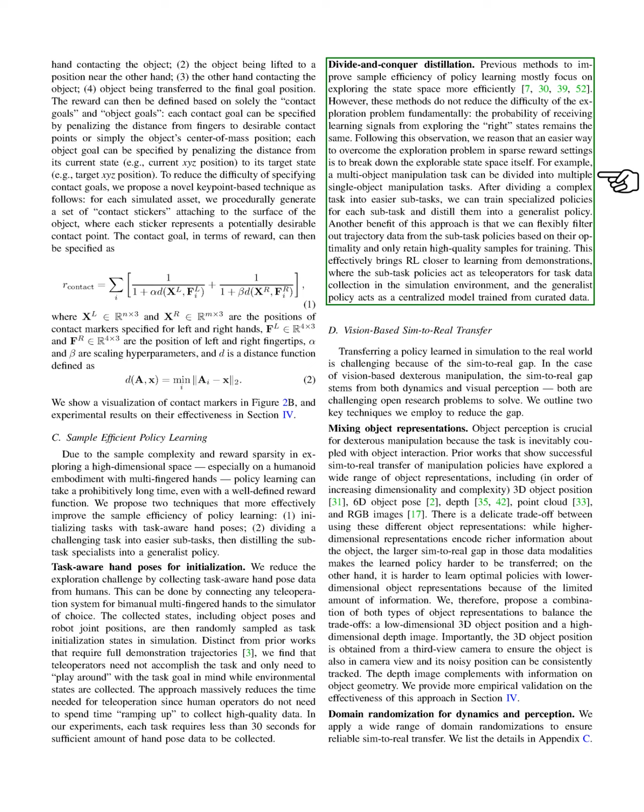In our divide and conquer approach, we suggest breaking down complex tasks into simpler ones, allowing us to train specialized policies for each subtask. We can then distill these into a generalist policy, filtering out only the best trajectory data for training. This method aligns closely with learning from demonstrations, where subtask policies help gather data in the simulation, and the generalist policy is trained on this curated data.